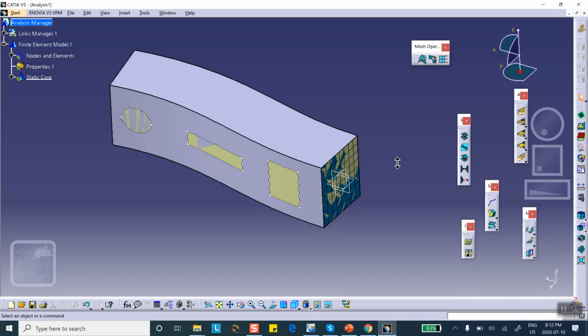Good. Now when you look at the three-dimensional elements, let me open this up. You have to do that in advanced meshing too. These are the standard tetrahedral elements, four-noded or quadratic. And this one is called sweep 3D. Sweep 3D means that you have a two-dimensional mesh like that, a shell mesh, and you're going to sweep it in a certain direction so that it fills the object.